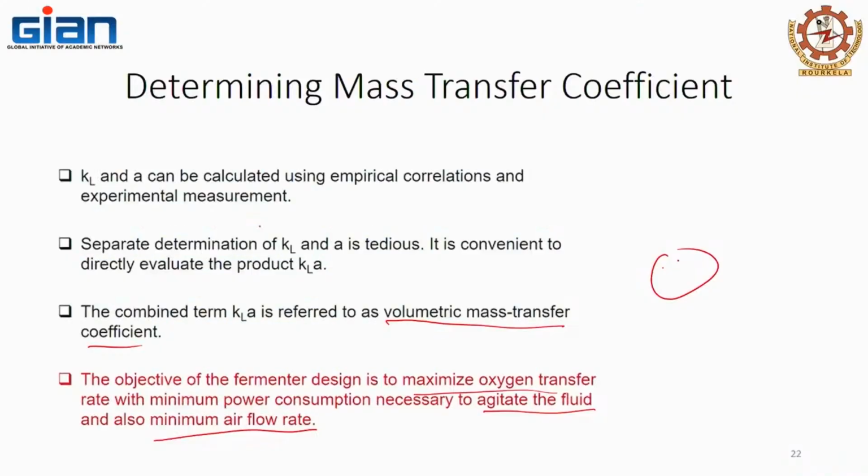So instead of agitation, we can supply the oxygen through a sparger, where the size of the nozzle can be reduced in order to reduce the size of the gas bubbles. Okay, so that means you want spargers with smaller holes, like atomizers. Very good, that is actually used. What else?